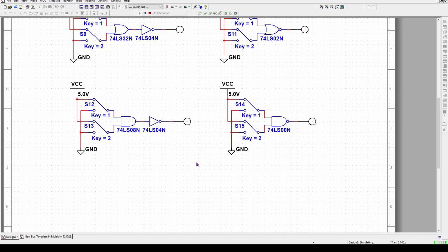I'm going to turn both keys off. What do we got here? 0 times 0 is a 0, inverted to be a 1, and the NAND gate is working correctly. Let's go 0 times 1, I'm sorry, I said plus. 0 times 1 is 0, so there should be a 0 after the AND gate, and it's flipped over, inverted to be a 1, and also true with the NAND gate.